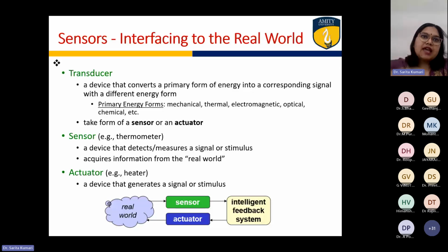If the tank has filled to the maximum value, the sensor will detect the level, and once it has detected that the level has reached a certain mark, it will give the signal, or automatically close the inlet. This closing of the inlet water is done with the help of the actuator. The actual work is done by the sensor sensing the level of the water, and once the level is achieved, the actuator will work and stop the inlet.